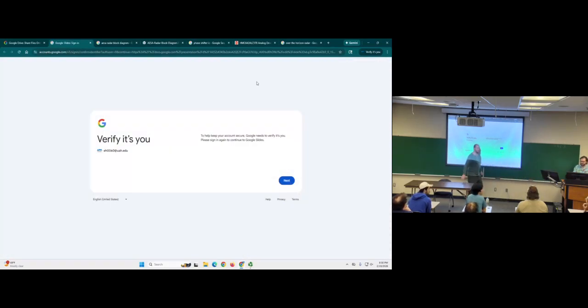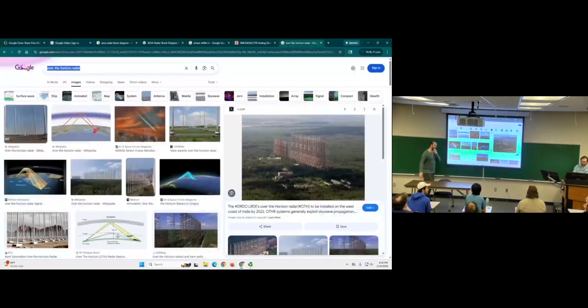You said the detector size is normally half the wavelength? For an antenna, yeah. So, for example, this is just a trick for radio stuff: 300 megahertz is 1 meter. So 300 meg is 1 meter, 1 millimeter is 300 gigahertz. So in that range, you can kind of visualize half of each of those, right? So at 300 gigahertz, your antennas are minuscule, it's half a millimeter. Good luck with that. As I said, energy attenuates as you go higher frequency.